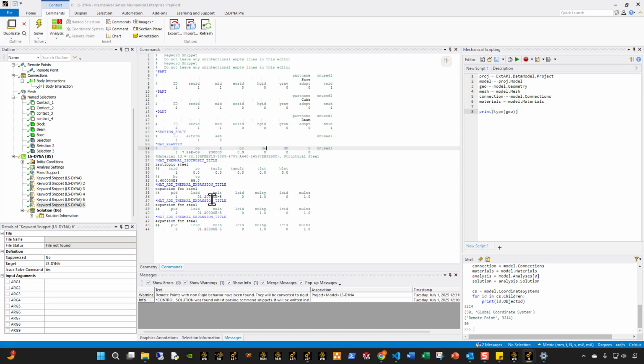But for the thermal material, right, I'm assigning them all to the same thermal isotropic material, which just has a conduction and a heat capacity, which is defined right here. I'm just making it simple. Obviously they can have very different thermal material models, right? They can have temperature dependent material models. You can add in here, and then for each of these, I'm gonna add a thermal expansion to each of these because it's a mechanical problem.